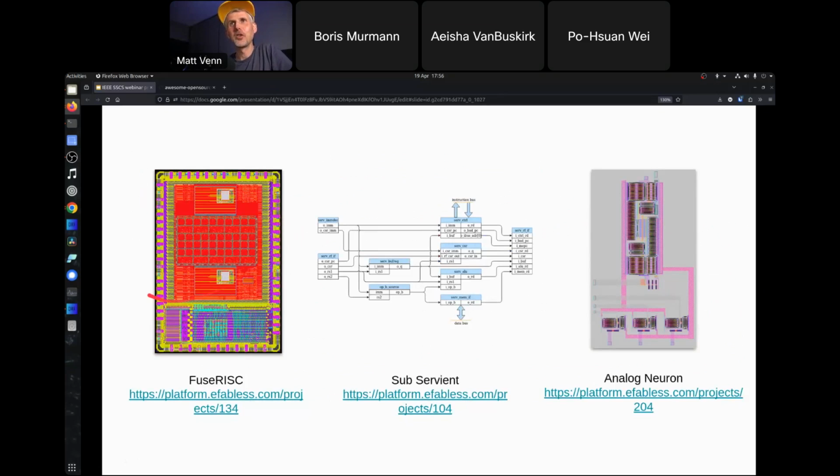Fuse RISC, really interesting. This is using the FABulous FPGA fabric, where you can basically make a Yosys compatible FPGA fabric, and it's been instantiated between 2 RISC-V processors. I think we're going to see a lot of stuff like this. If you're in industry, you buy an off-the-shelf chip, you use it, but probably you're only using like 20% of its peripherals. A lot of that silicon remains dark, but you still had to pay for the silicon. So there's a good niche here. If it becomes easier and easier to do SoCs with a bit of FPGA, a couple of RISC-Vs, a bit of mixed signal, just for your application, you know, Nordic Semi only moved away from 130 nanometers a few years ago. There's still a good niche here for doing industry compatible stuff, especially with mixed signal.